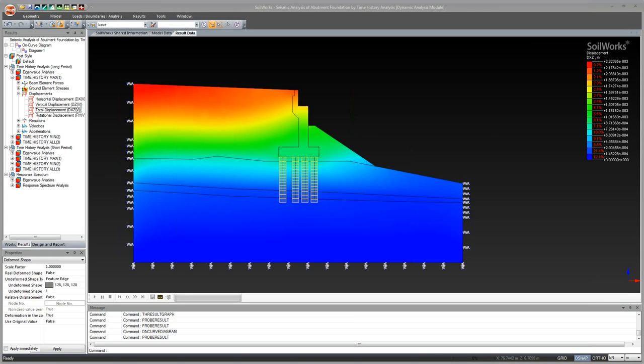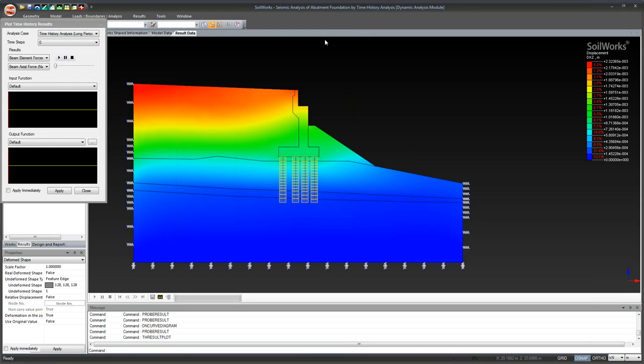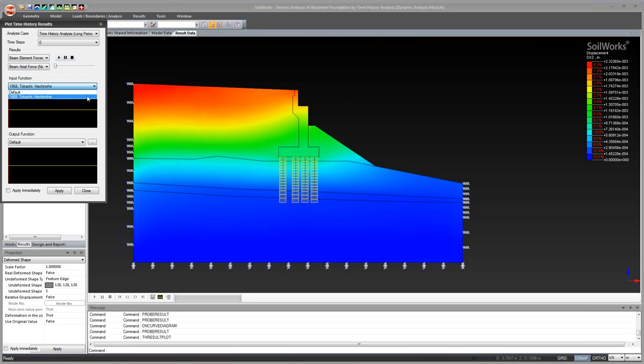And then, for those of you who want to draw your time history, let's say you want to see how the results change at a specific point of the earthquake, or along the time history function. Go to results, and then go to draw hysteresis. Go to this function here, and make sure to select your time history function. So let's select our first set, and let's select not the axial force, but the displacement again, vertical displacement. And just use your mouse cursor to move along the length of the earthquake.